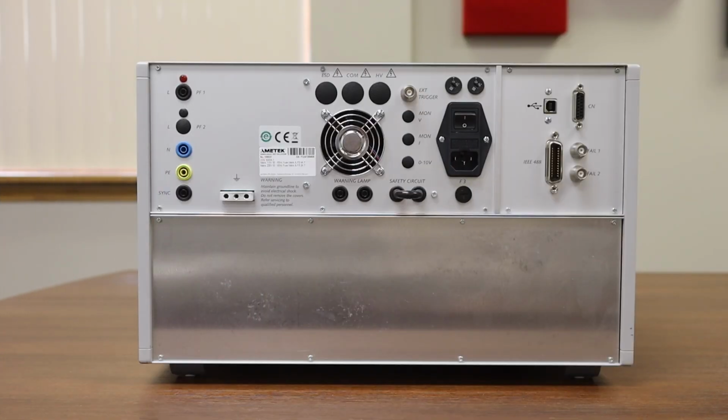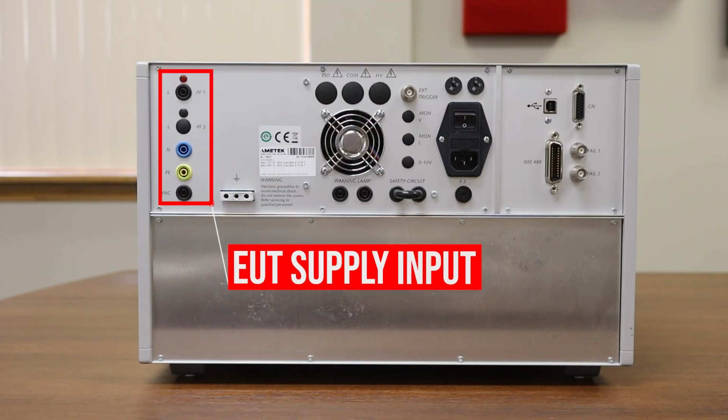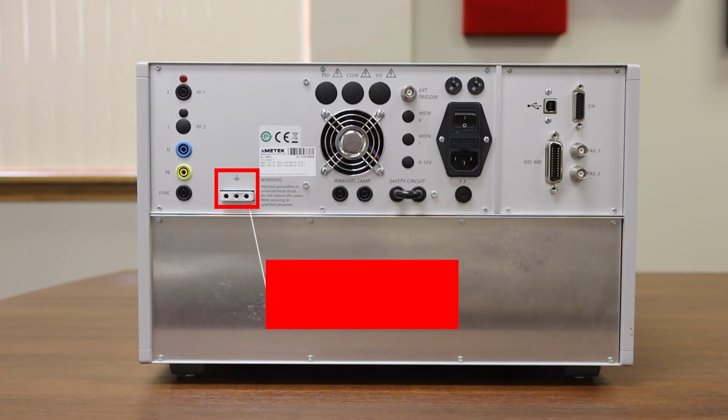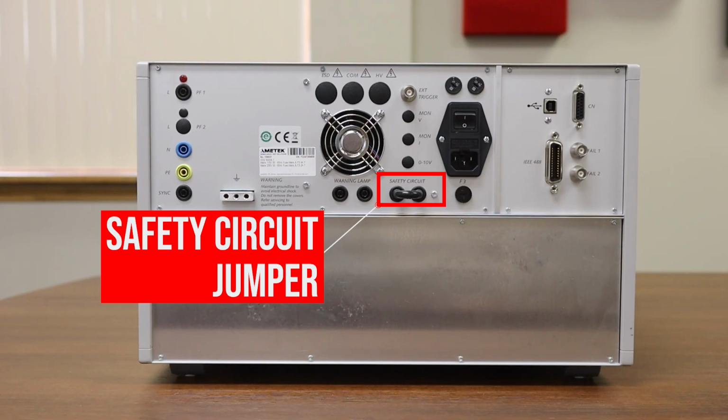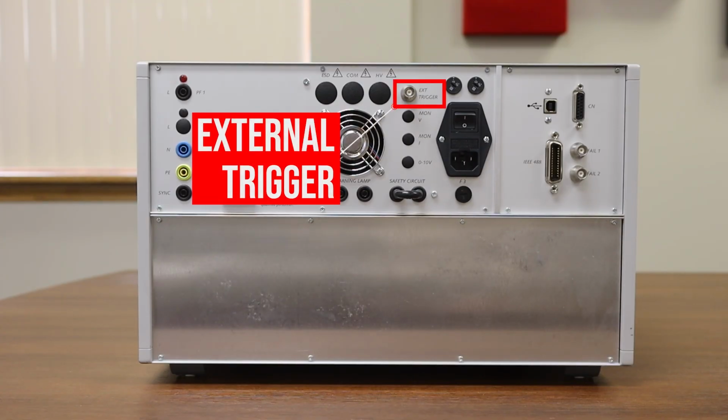Here's the back of the OCS 500N6. Starting on the far left, we have the EUT supply input. Next to that, the reference earth connection. As we continue right towards the bottom, we have the safety circuit jumper, which needs to be connected for the system to operate. And just above that, we have the external trigger.